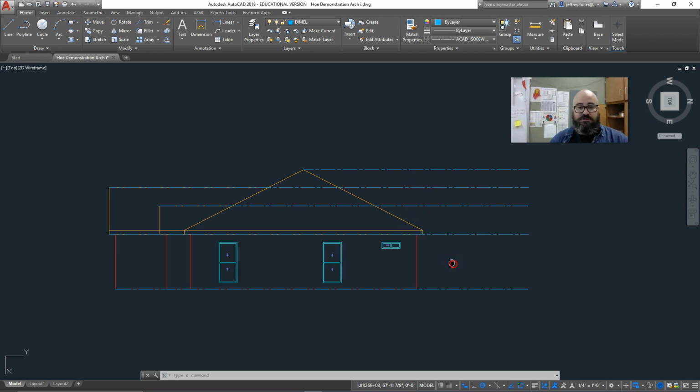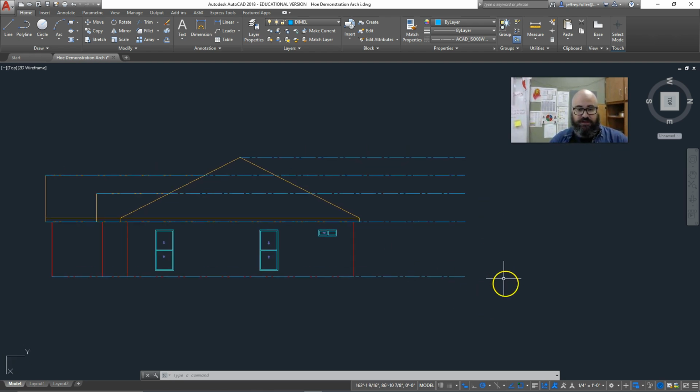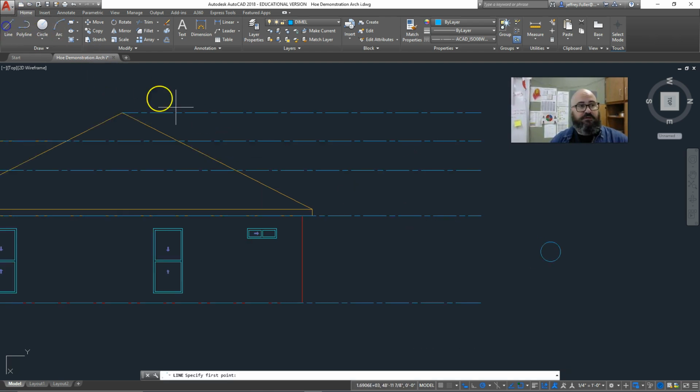The next thing you're going to do is create the symbol that goes to the end of that line. And I do that by just creating a circle, and I just made a 1 foot circle. 1 foot, and I don't remember if that was, I think it, let's see, what does AutoCAD do? Radius or diameter? Okay, it's radius. So basically 1 foot radius, 2 foot diameter circle. And then of course I fill in the middle of it, just using some of my snap guides to make sure I get in the center. And go back to line tool.